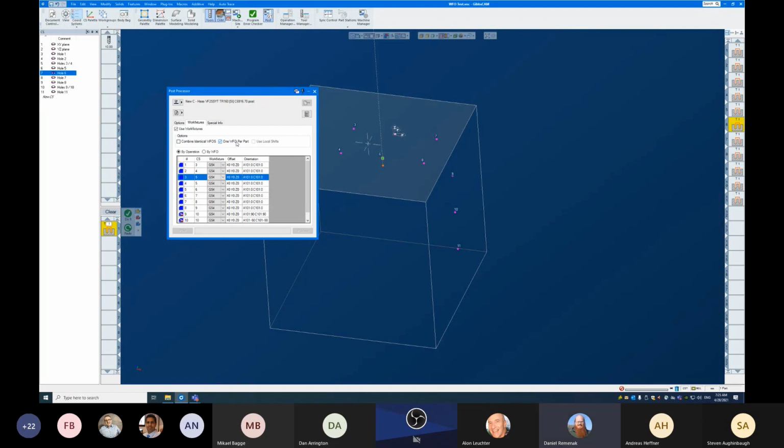If you're dealing with multi-part, you get some additional advantages, and there's actually a separate icon. So this blue icon means this is the part instance, the G54 in this case for this post processor. We also have another icon that we'll fill in here if we're on an instance CS for a mill multi-part scenario. And in that case, you might run out of work fixtures relatively quickly, and you may want to assign certain operations to share work fixture offsets between parts.